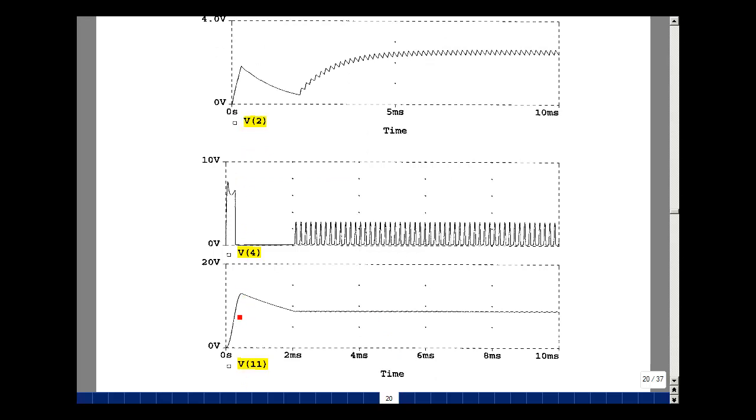But there is a power diode in our regulator. It's called D1. It's an MBR1035. It's a power diode, and it has a time delay. It can't switch instantaneously. So you're actually seeing a little bit of a time delay before that can kick in. When that happens, the transistor Q3 is cut off, and now our switch is open, and we begin to RC decay with the capacitor and resistive load. But eventually we come back down to this 8.9 volts roughly, and you can see that things begin to happen. And we've kind of reached some stuff in steady state.